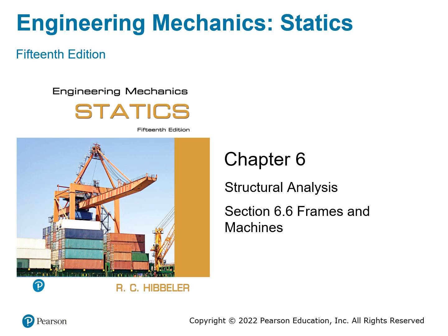Previously, we were looking at the definition of the truss, which is a simple triangle structure with members that only have two ends that will be connected. We also talked about two different methods to analyze the structure. The first is the method of joints, where you use summation of F at each one of the joints to find the force in each one of the members.